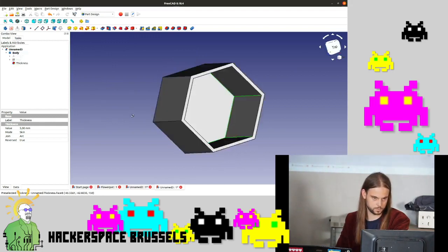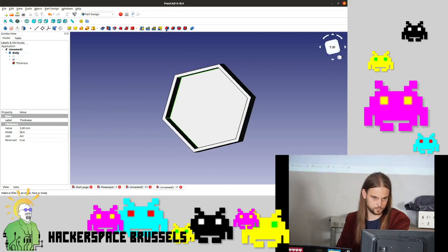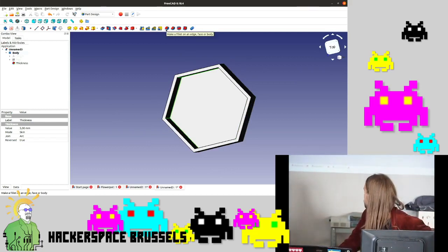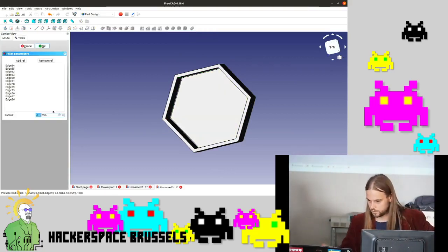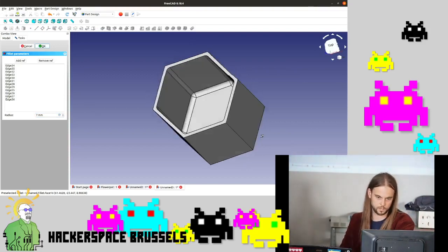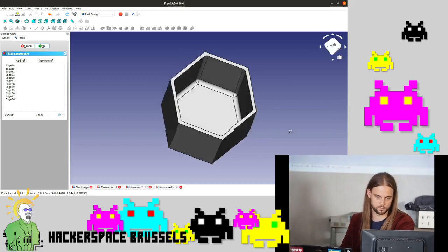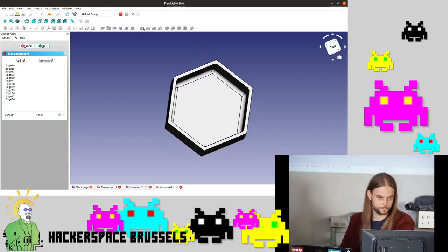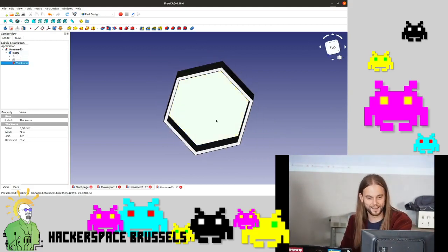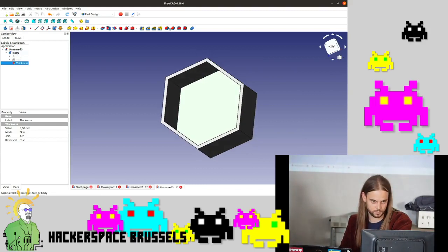Alright. Then we click the make a fillet on an edge, face or body button. And we'll give that a value, for example, 7 millimeters. That gives it a nice little smoother edge on the inside, as you can see. Which button? Oh, of course, you lost my selection. Fillet, which is on top, the red and blue one. Yeah, it is a bit small.